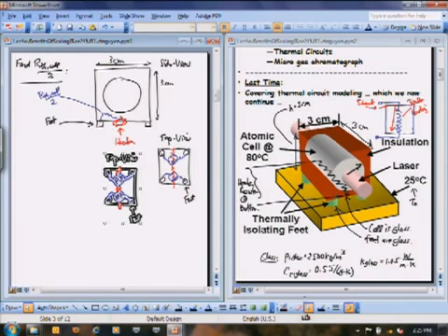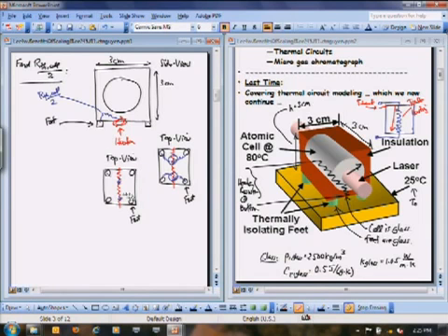I'm going to say this whole thing here is just one long heating source, right? And I'm going to say I've got one resistance here and another resistance going that direction, and this resistance is going to that where there's 2 feet. So I've divided this into just this very simple, almost one-dimensional problem here. Okay? And that's how I want to attack this problem.